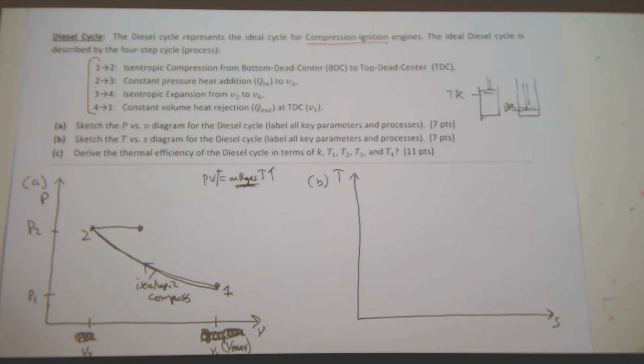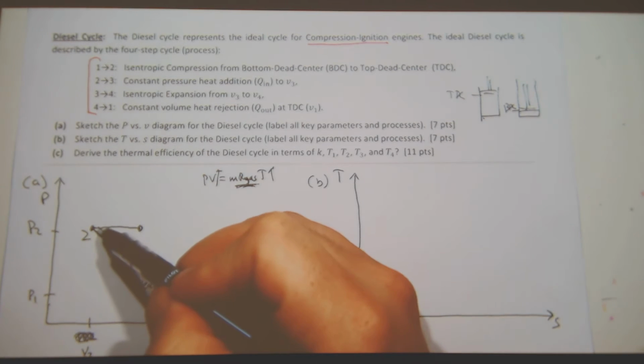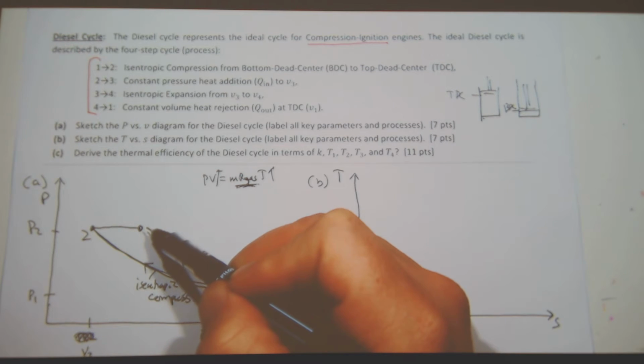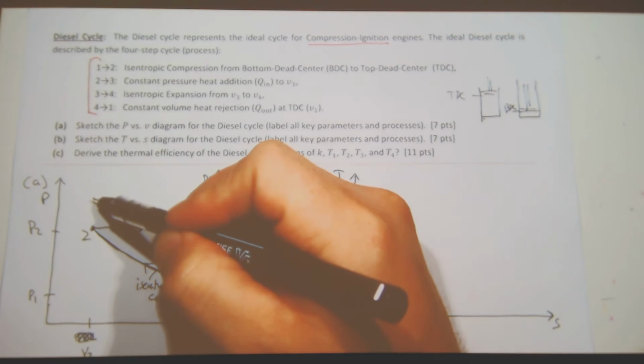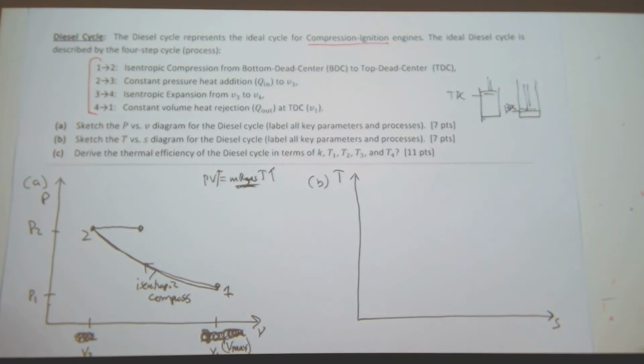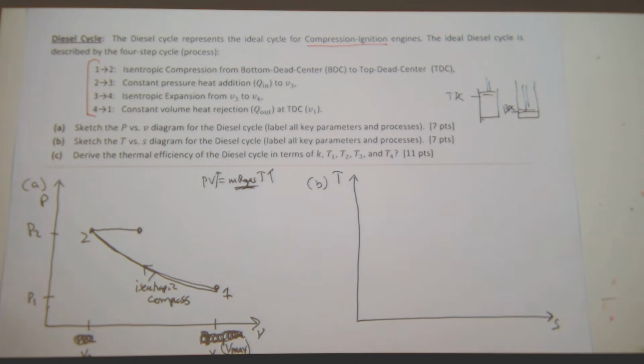Okay, so I'm glad you asked that question. So the question is, it doesn't seem right, this type of drawing. I'm compressing to auto ignition, but then I'm not getting an increase in pressure. All I'm getting is this instantaneous increase in volume at constant pressure. Now really you should compress it, you get combustion, an increase in pressure, an increase in temperature, and so you would expect some 3 above, like an Otto cycle. This is the ideal diesel cycle, not the real diesel cycle.